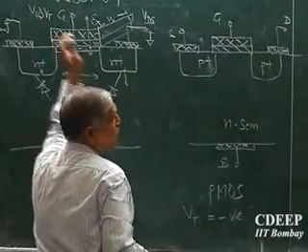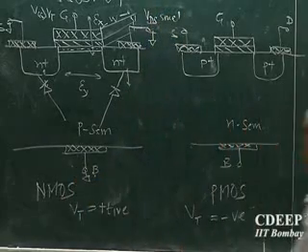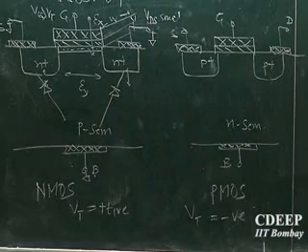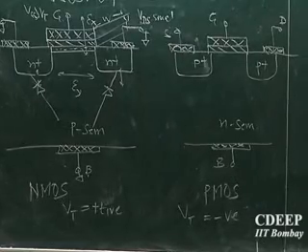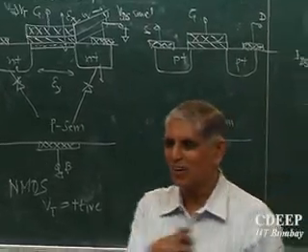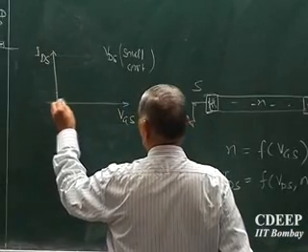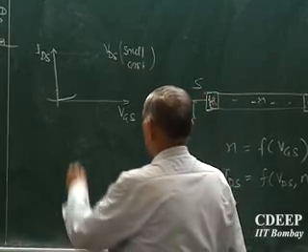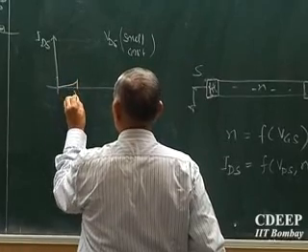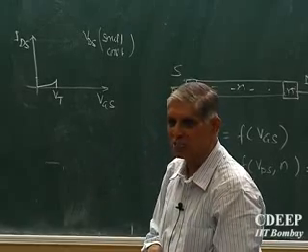Okay, so if I apply VGS and I apply VDS small, and bulk of course I always ground right now for all devices to come, then if I make VDS 0, there is no current from drain to source. Is that point clear to you? If I make drain source voltage 0, no transport. So I need VDS for current to flow. Now if VDS is very small, and I increase VGS, I see a very small current till a certain voltage, which I call threshold voltage. Now can you see why this current exists even below VT?